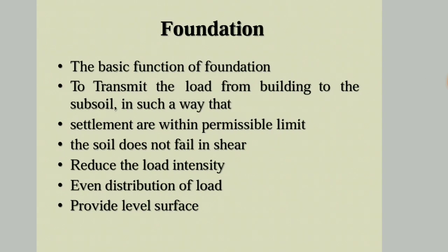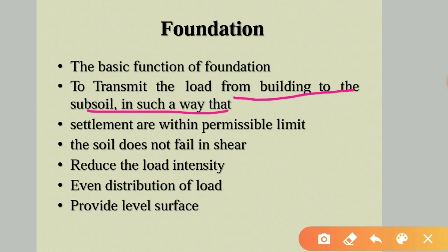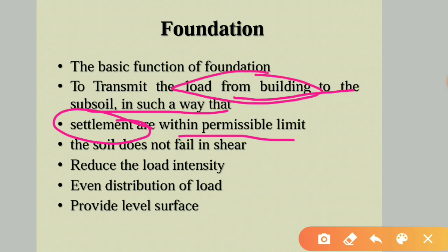Next, coming to the foundations. The basic function of the foundation is to transmit the load from the building to the subsoil in such a way that settlements are within the permissible limit. So in order to transmit the loads and also to minimize the settlements, two functions are there. First one is load transmission. Second one is settlement.